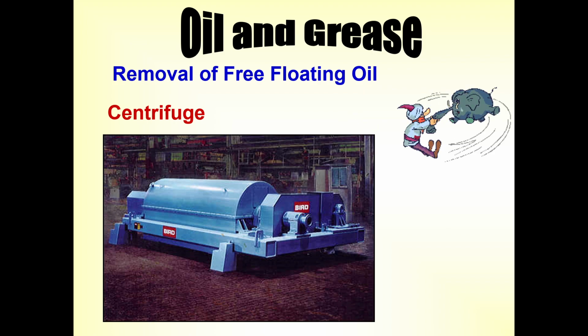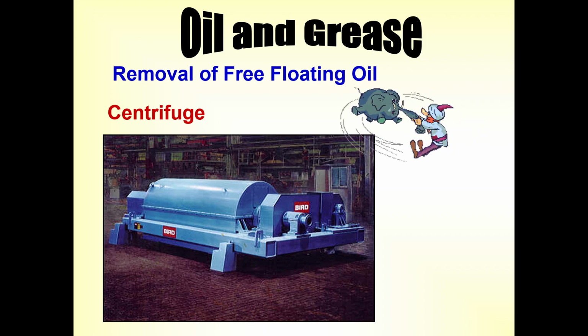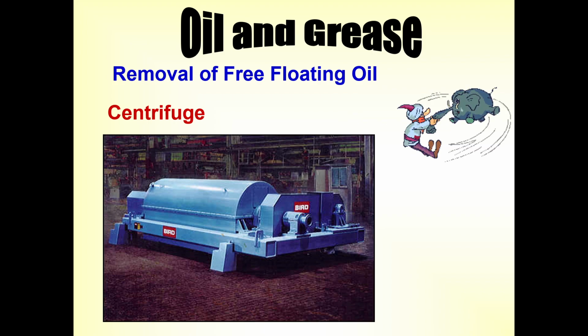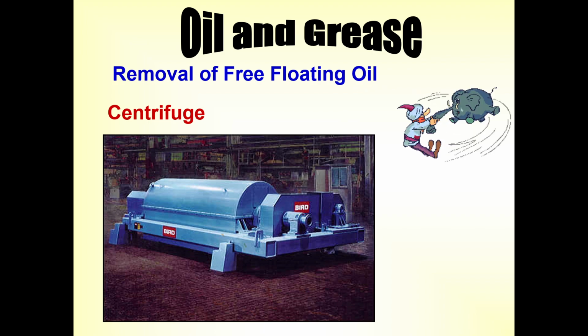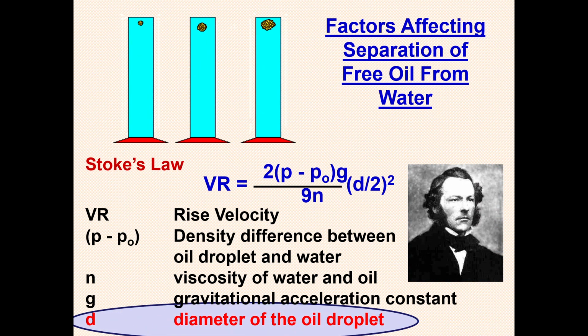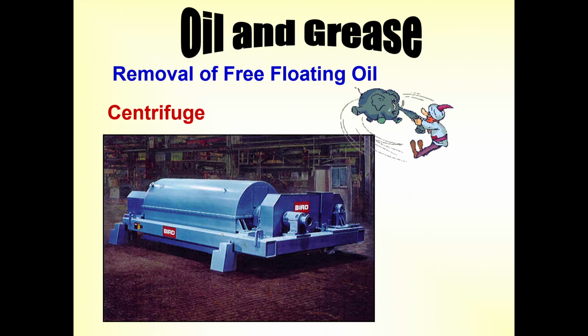Next one is how we are separating this oil and grease when we take the centrifugal method. What is meant by the centrifugal method? Normally when a particle is rotating, centrifugal force will be acting. The centrifugal grease extractor will have a series of baffles, I hope you can understand this. This we have already seen. Baffles will be installed in the exhaust hood.